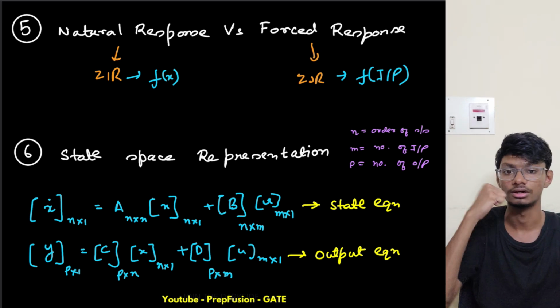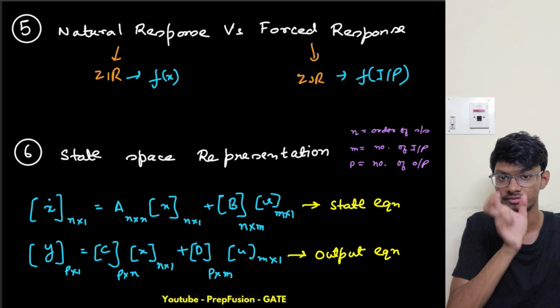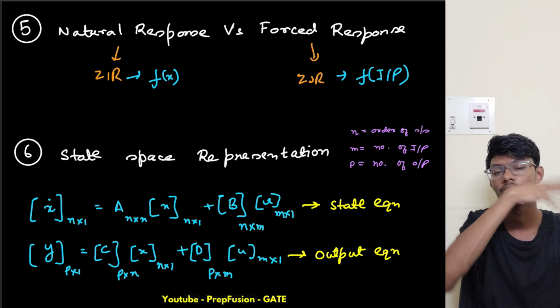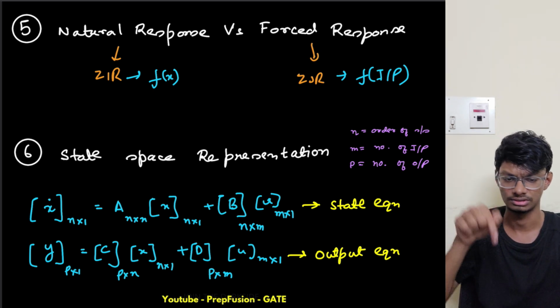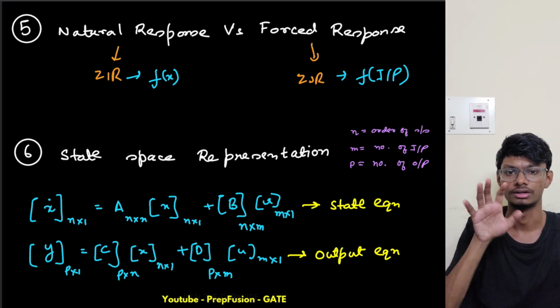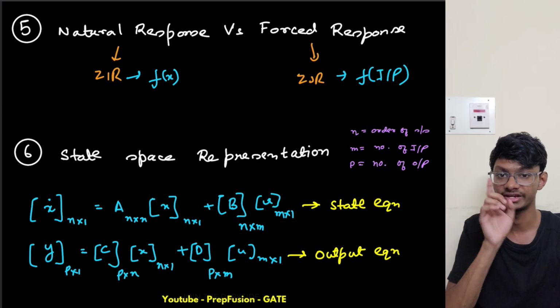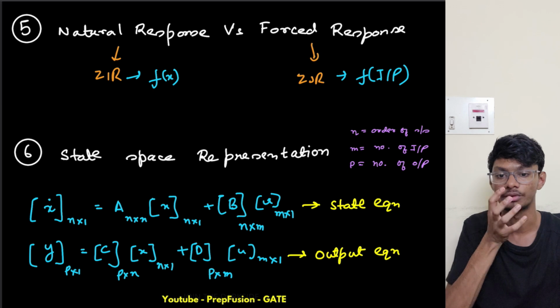In the basics also, I think I gave you a brief overview of stability. A pole lying on the left hand side will make the system stable, a pole lying on the right hand side will make the system unstable. In state space also I maybe did a few examples of that, right? So with the A matrix, very important, I can tell the location of the poles.